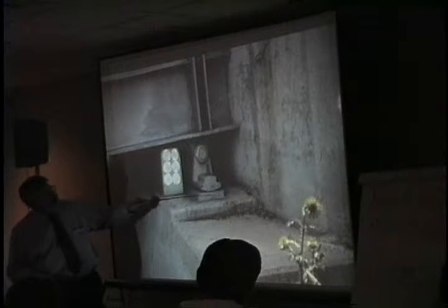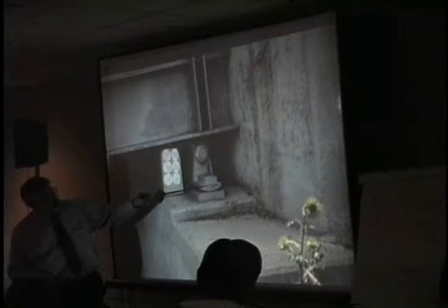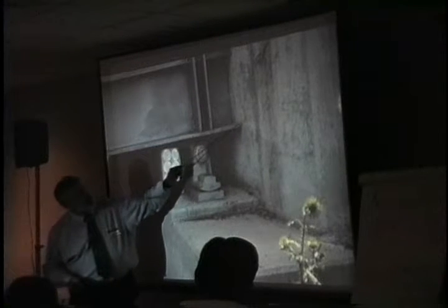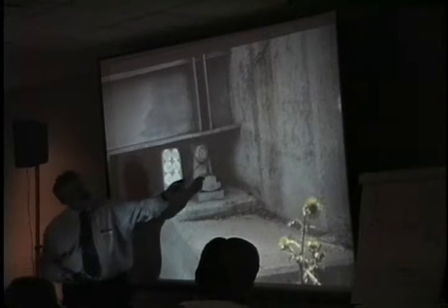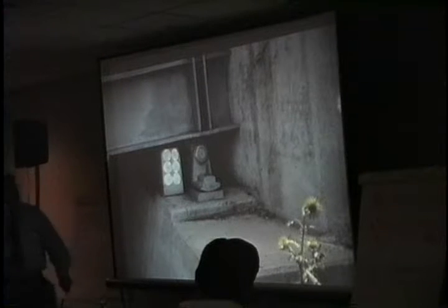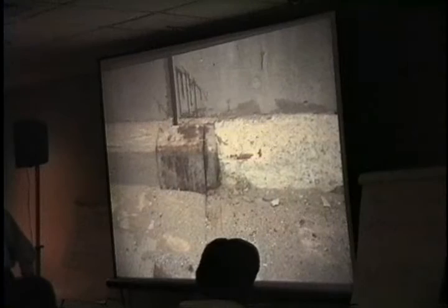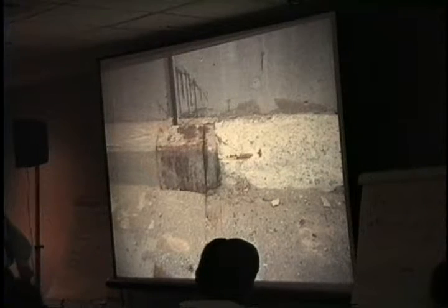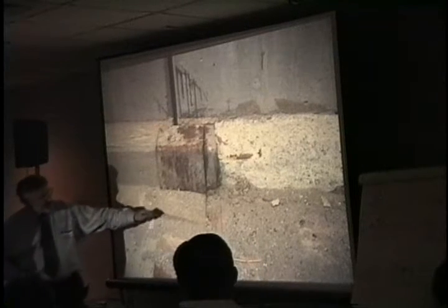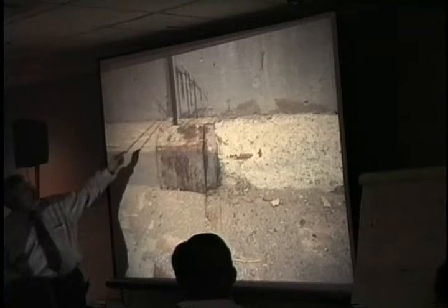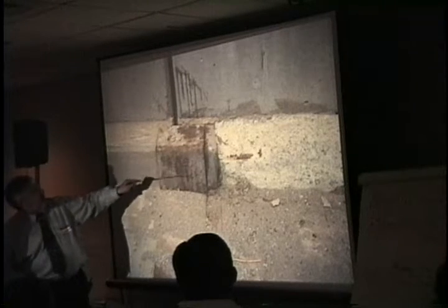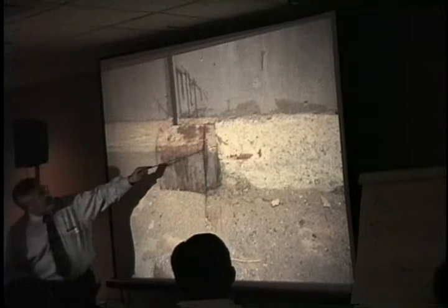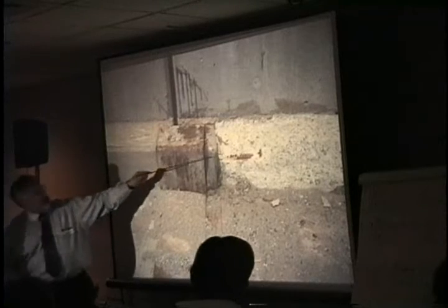The top has moved back a bit. The girder is right up against the back wall. Expansion joints are closed, partially open. This is a lot of corrosion.